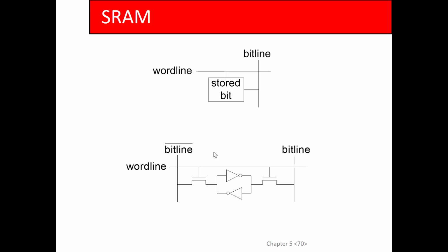But that's the most you can fit. And by the way, the cache is like over half the chip. If you look at a photograph of a processor, half of it is processor and half of it's cache. So you take half of the real estate of the chip and you just put these SRAM cells on there, and you only get 32 megabytes at most. Most consumer level chips, by the way, are much smaller, like 8 megabytes, right?